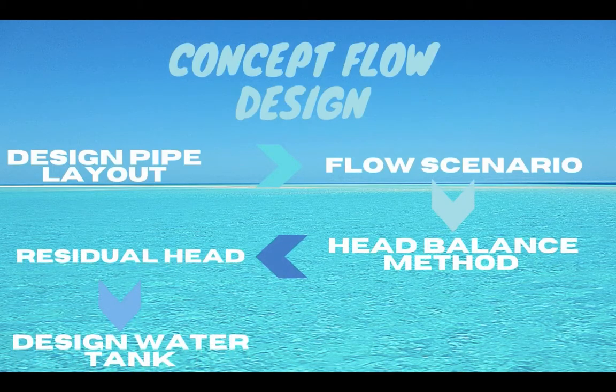Okay, this is my first slide. This is the concept flow design. Before we design the water reticulation, we need to know the concept flow design. We have 5 steps. First step is design part layout. Second step, flow scenario. Third, head balance method. Fourth, residual head. And lastly, design water tank.